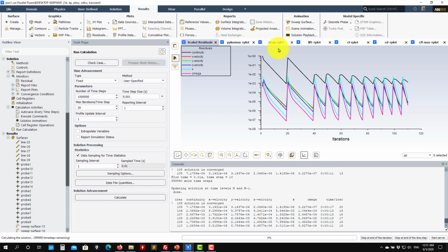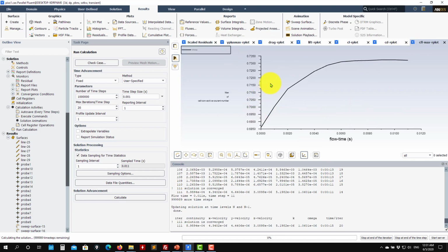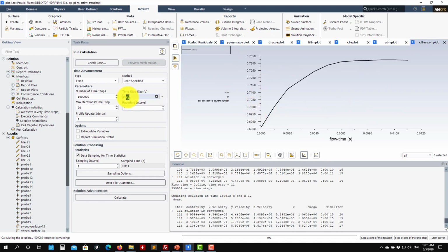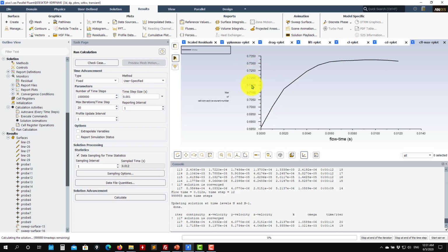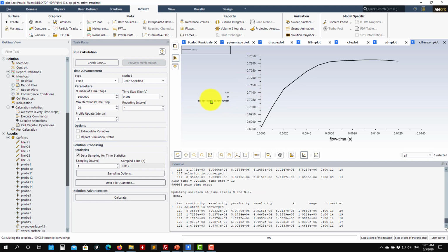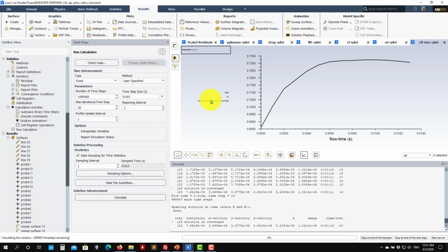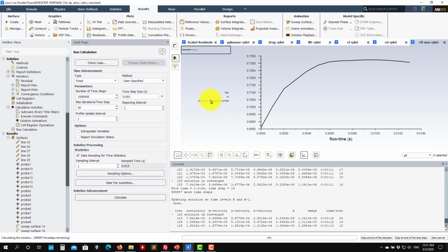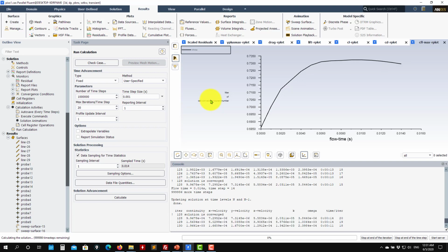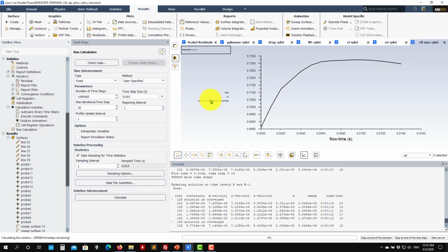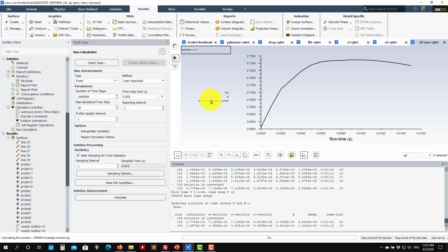As you check here, you have it here, CFL max. Okay, in this case it didn't take the modification we had. See that 0.7, so this is good accuracy, but we can go larger in the CFL number with no problem. As you go larger, you can advance faster, but you might lose some information in the solution. So I will let this simulation run a little bit, and let's see what happens later.